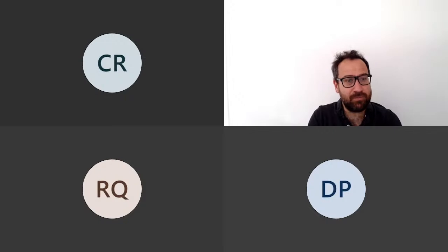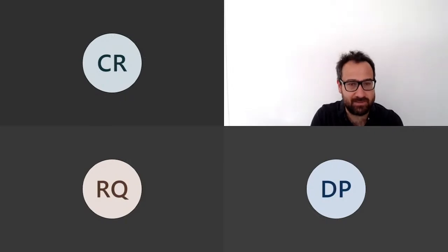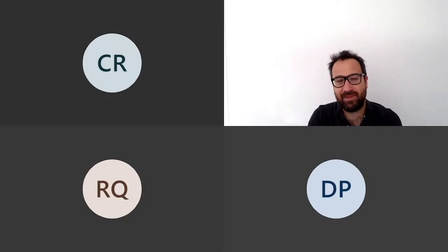And a lot of the demand response systems that we have, a lot of the automations that, instead of managing supply, manage demand, actually operate on that premise. So they look at the frequency and they can act immediately, either by reducing demand or increasing demand, if there is an issue with the frequency, and that is seen as the best fast response way to balance the grid.